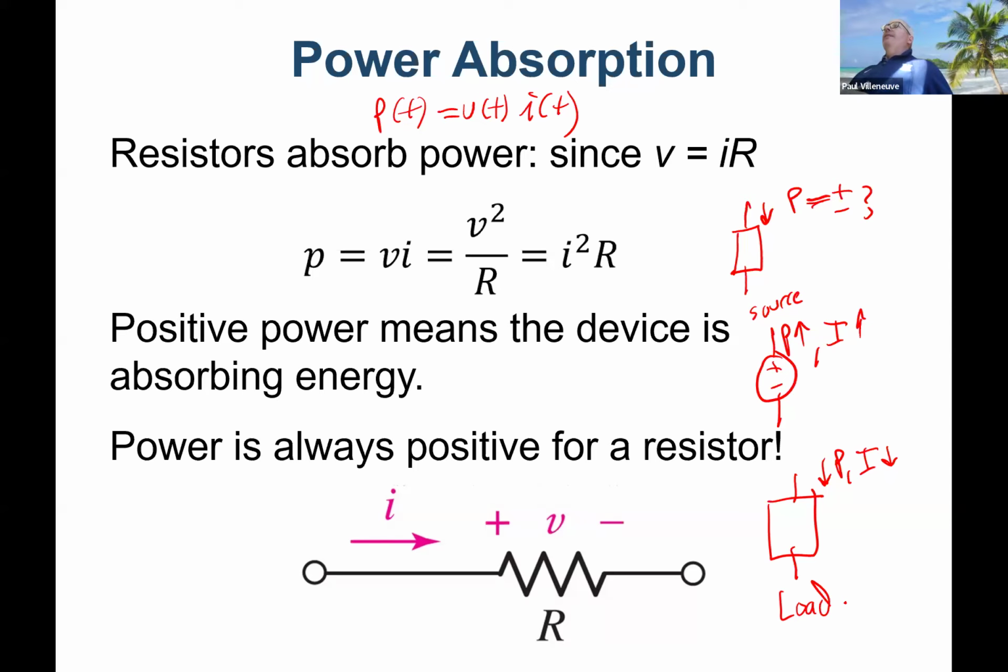No. How about the work? Can you ever have negative joules in a capacitor? No, the energy has to come from somewhere. So when you're analyzing a circuit and saying, well, my capacitor has negative 12 joules of energy stored, you might be like, uh-oh, where did I get the joules from, right? That's not going to work so well. So you can get to zero, but you can't get negative.